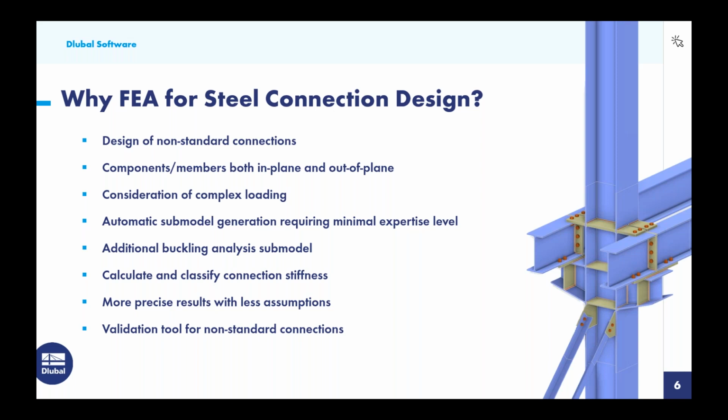We also create an additional second submodel for the buckling analysis to carry out that eigenvalue analysis. Oftentimes, an eigenvalue analysis can be very difficult to calculate by hand, for example. So by utilizing FEA, we can certainly take a look at the buckling behavior itself.